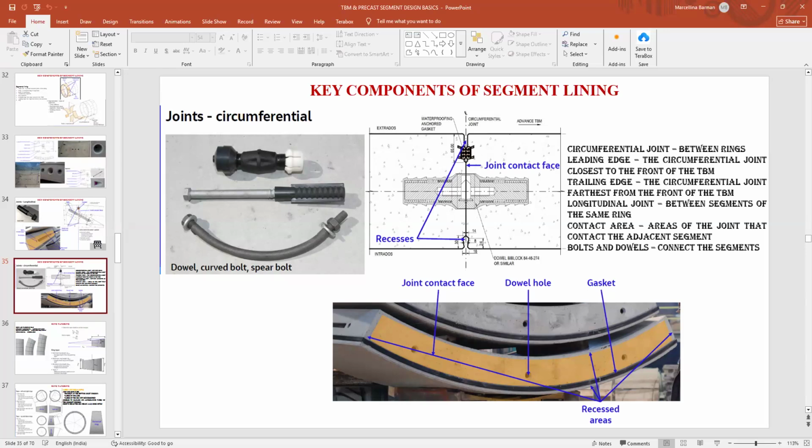Sir, regarding bolt, temporary and permanent. In which case can it be temporary and in which case can it be permanent? In my experience, in all the projects we never remove the bolts, but in Delhi Metro, in some of the initial phases they removed them, because after all the segments are joined, they make the perfect circle, so automatically they are connected. So you don't need the bolts. It is nothing from the structural point of view that the bolt has to be kept or has to be removed.